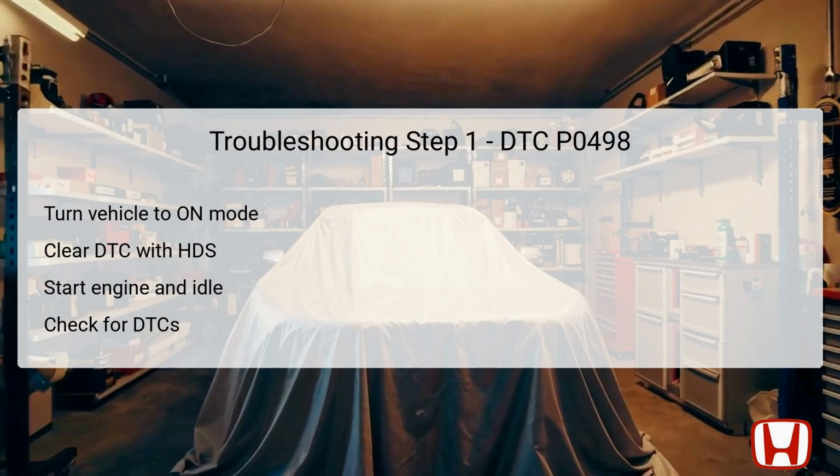Once cleared, start the engine and let it idle for at least 5 seconds without loading it, such as being in gear. After this stabilization period, again check for any pending or confirmed DTCs using the HDS. If DTC P0498 reappears, this indicates that the issue has been duplicated, necessitating further investigation. However, if no DTC is present, one must consider the possibility of intermittent faults that could be due to poor connections or loose terminals.